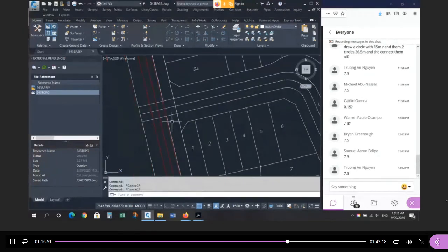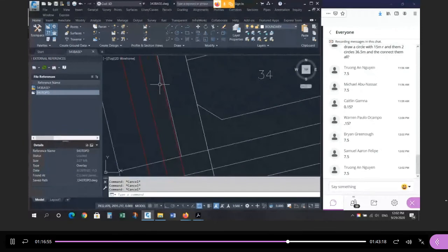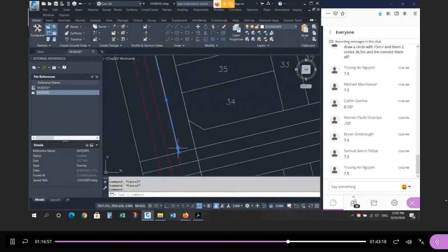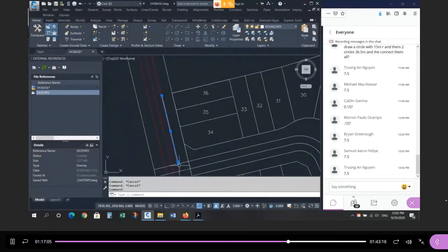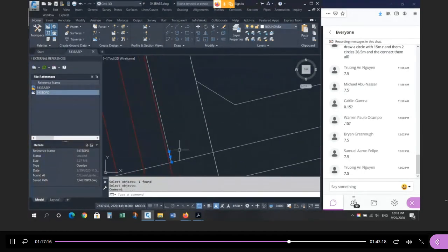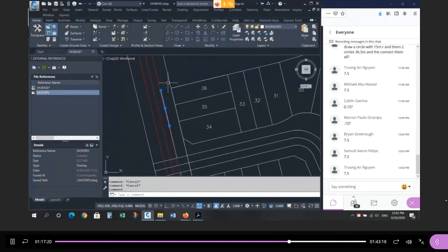So now I have a piece on this side and I have a piece on this side. And when you fillet, be careful. Right? There's a little piece here. There's a longer stretch here, and then there's a longer stretch here. Am I going to fillet against this short line or this longer line between this and this dot? Or do I have to go all the way in this? There's 3 line segments here. I'm going to explode them. Do I fillet against this or this or this? And these aren't necessarily parallel. They look like they're all in a straight line, but they may not be.